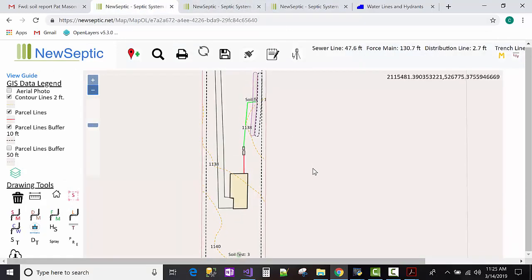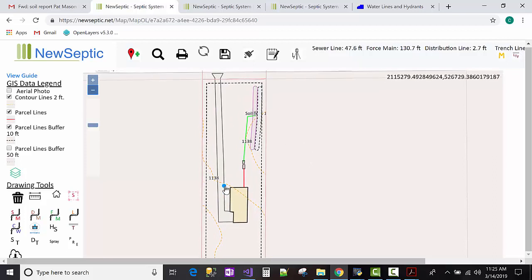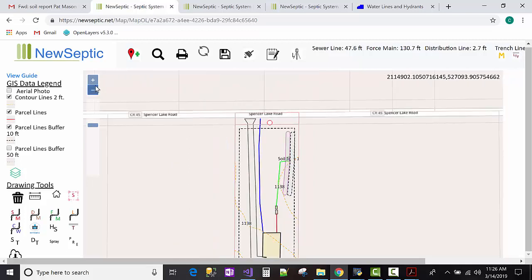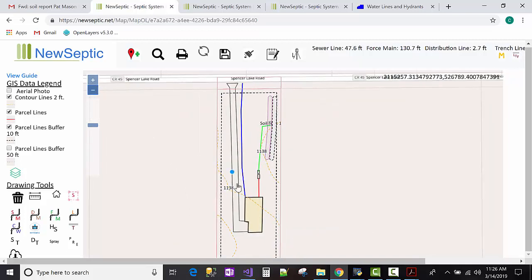and I'm going to draw a water line to parallel the driveway. So what I'll do is click on that CW, which is a city water, and I'm going to go ahead and just kind of click a line there. And it looks like I did pull this off here, so I'm going to move this out. Sometimes the snapping is a little bit tight, and we're going to work on that. But so I'm going to pull this sort of close to the driveway, and that would be a representation of our city water line access.